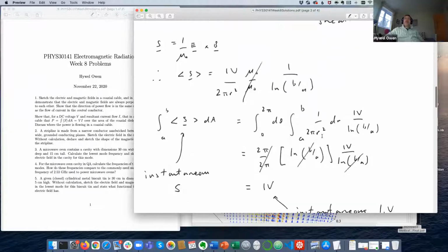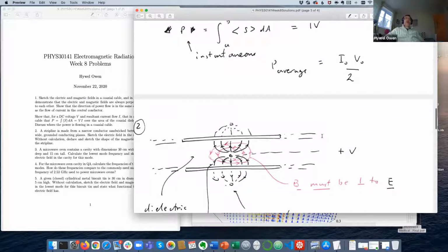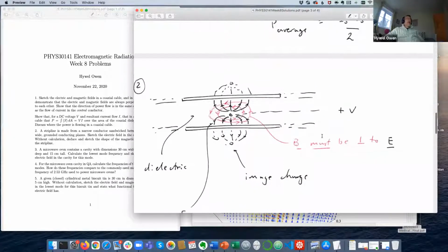Now let's look at question two, which is a graphical question which illustrates this idea a bit more. Now, I wanted you to look up what a strip line is. In our derivation of the strip line equations, which of course is a modification to the transmission line, we talked about microstrips, because a microstrip is the situation of a finite width but thin layer of conducting material lying above a large width ground plane. So that's our idea of the printed circuit board.